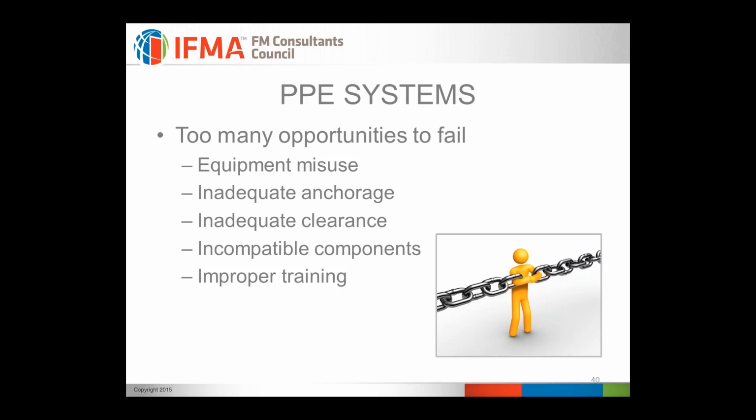The same goes for fall clearance. I can't tell you how many times I've seen people using a system when they're maybe 8 feet off the ground, and they're using a 6-foot energy-absorbing lanyard that is connected around their back, roughly at the level of their back D-ring. Certainly, if they were to fall, that lanyard would do them no good whatsoever.